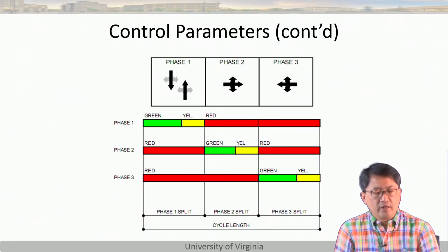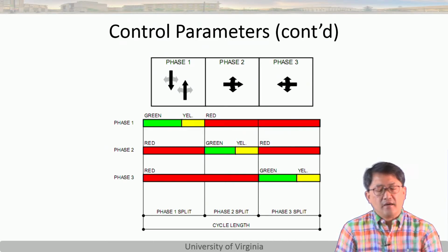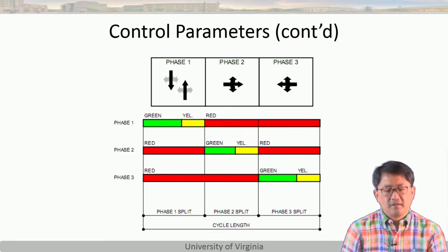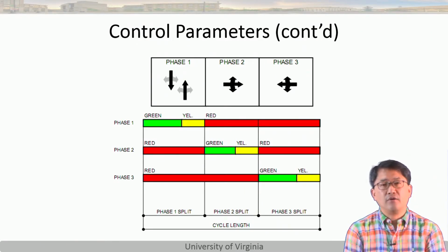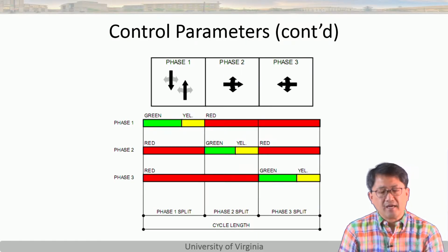This is a typical way of doing phases. This is without having pedestrians, so it's fairly easy to give phase 1 and phase 2 and phase 3. The ones that are not dark black are permissive, so they do not get a left turn arrow or right turn arrow. They can just make their own way of making turns. It's fairly common as well, especially when you have a single lane per direction.